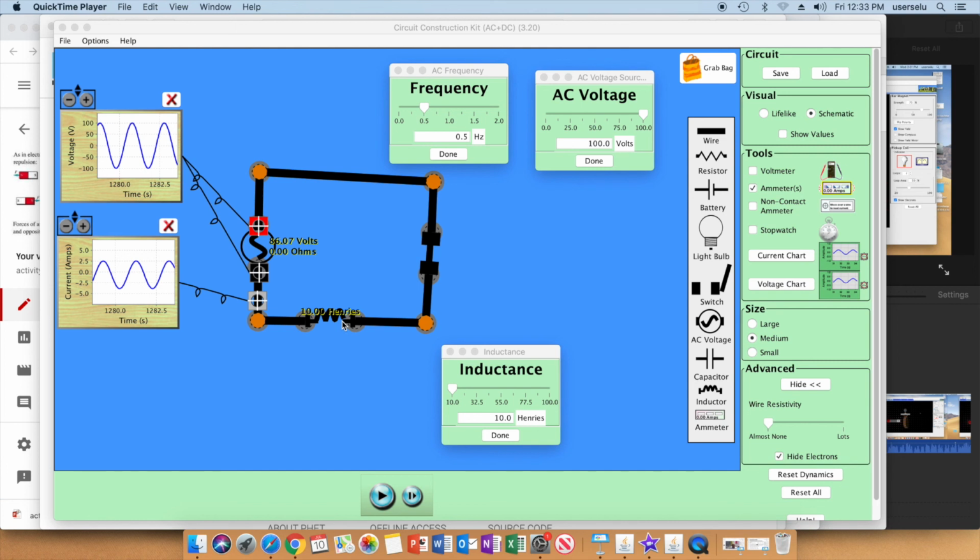It'll do it for a fraction of a second while the current initially begins to flow, but once the current is steady in the direct current circuit, then the flux doesn't change through the loops, so now the inductor no longer provides any resistance at all. Only in an AC circuit where the current is constantly reversing do you have a constant change in flux of the coil loops, so that you have a constant change in back current, pushback resistance provided as it tries to oppose the change in flux that it experiences as current flows through the coil.